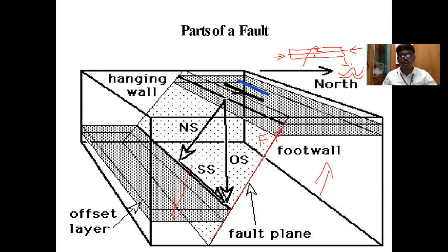And whatever the slope you see where the fracture plane has happened, that is what we can call a dip or true dip. To be precise, I'll try to draw with respect to this strike. So you can see this fracture plane and the dip are the same or parallel. That's the third point I've mentioned. The true dip will always be along the fracture plane with a maximum slope, right? So I hope I'm clear on the first part of the fault.